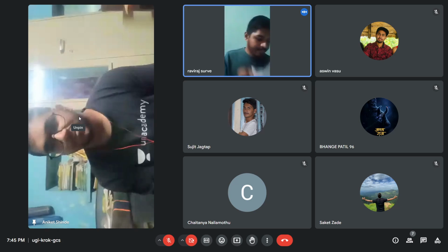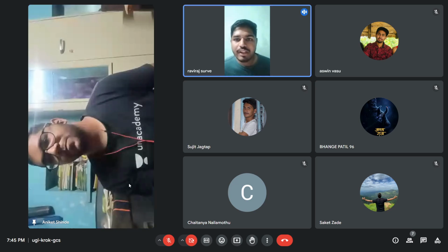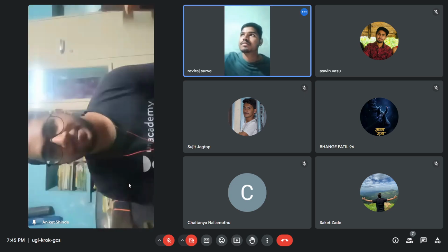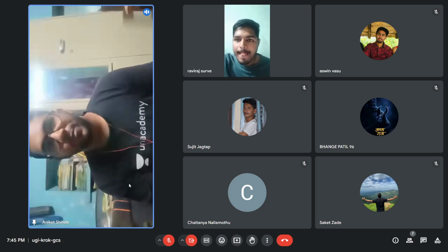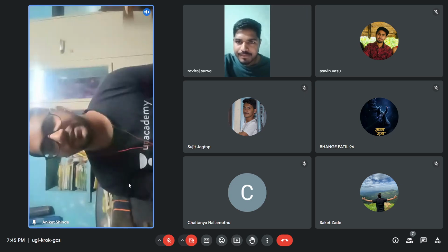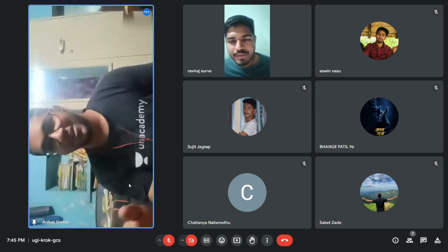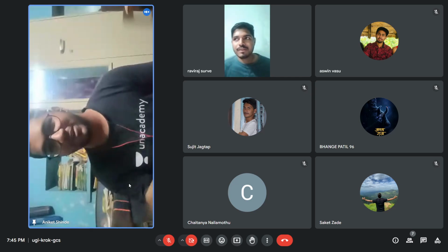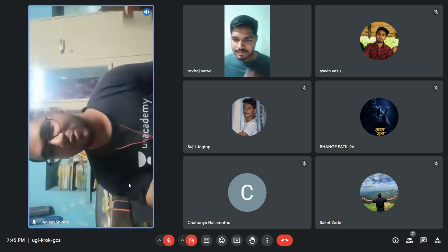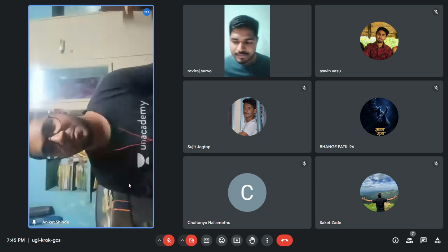Just a minute, Aniket. So, Aniket, can you tell me what is the function of rocker arm? So the main function of rocker arm is to control the openings and closings of the exhaust and inlet valves, and it is connected via cam lobes to the camshaft, and it helps in the opening and closing of the exhaust and inlet valves in the IC engine.